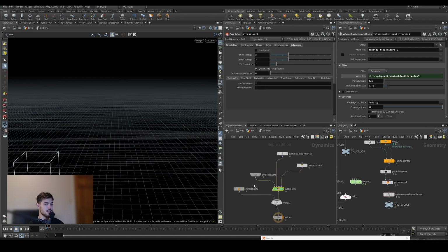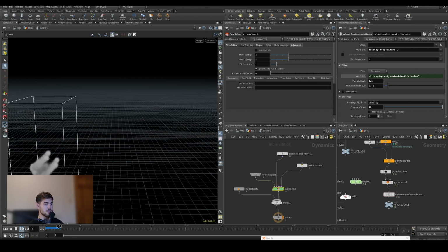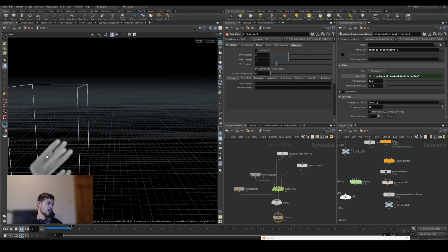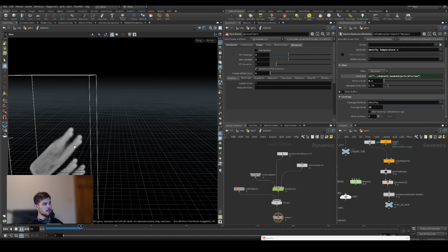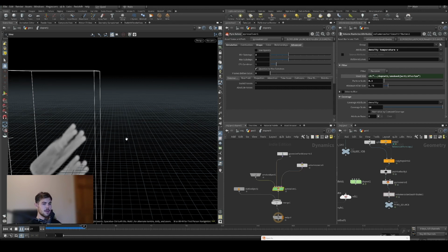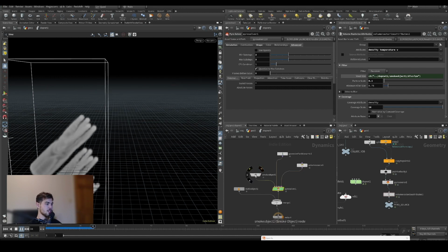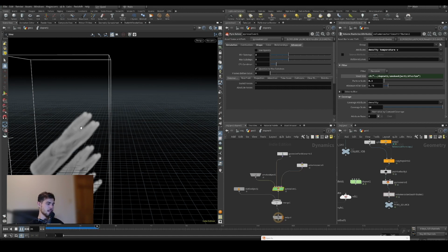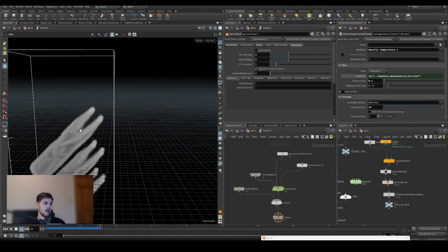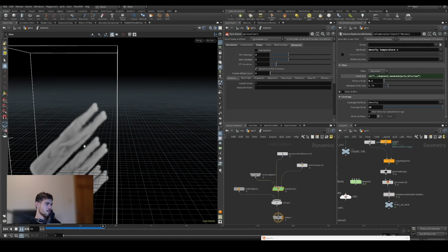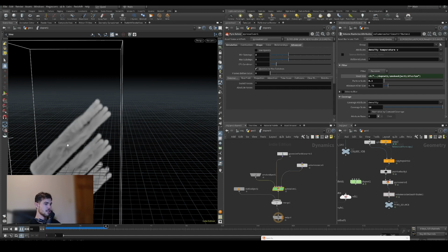And so that should kind of give us the starting point for what we need out of the simulation. And for making this look nicer, we can increase or decrease the division size, increase the resolution of the simulation, and we could also potentially play around with the density values that are being sourced in.